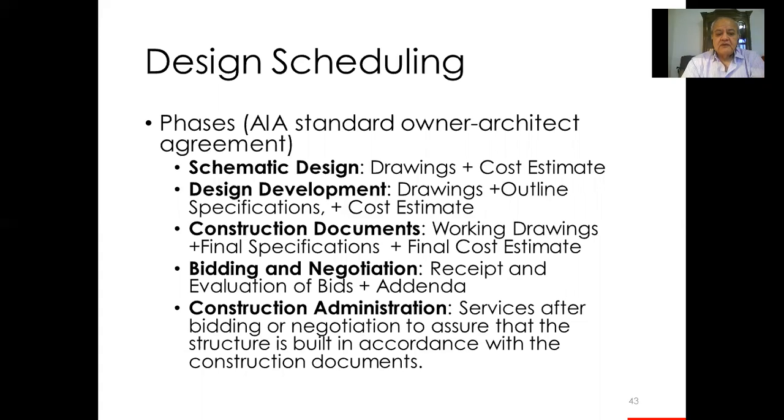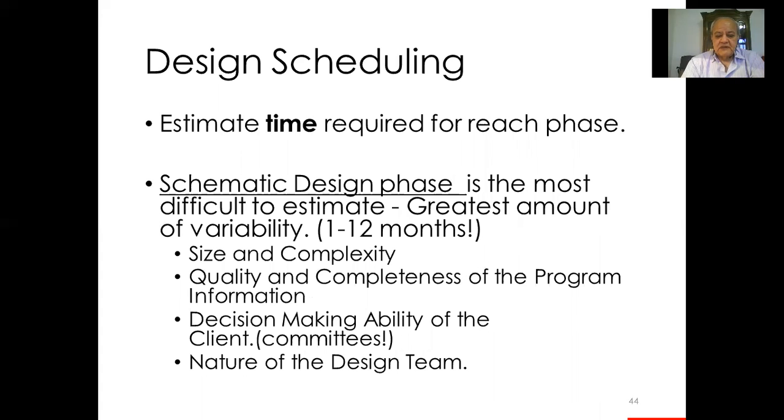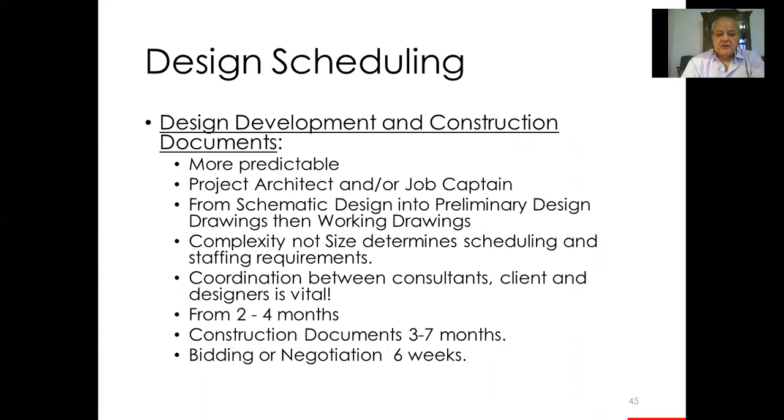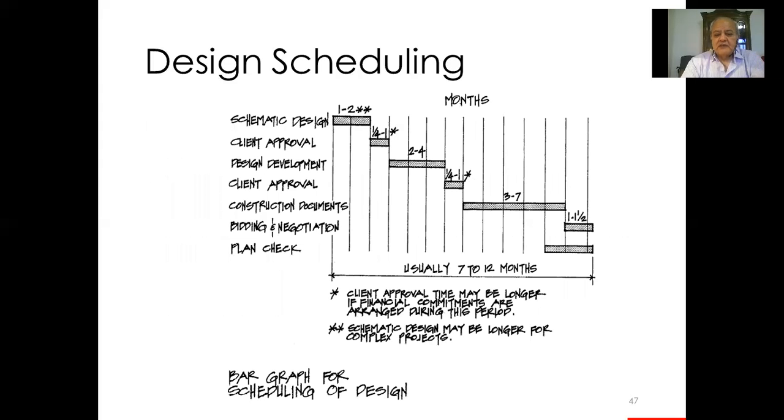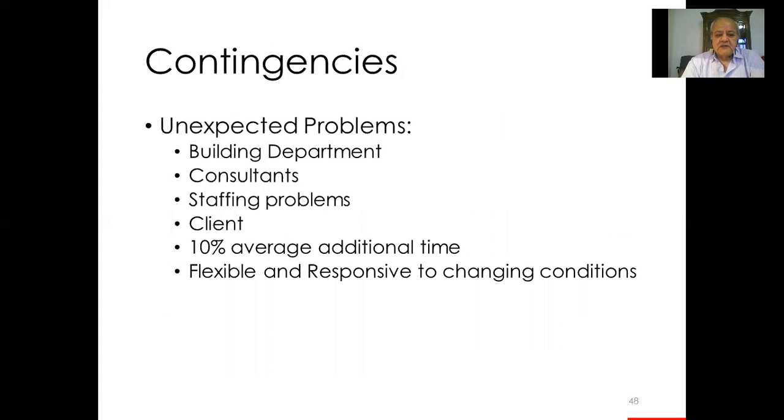We have to provide the owner with a schedule that covers these periods of time so that they can follow the progress of our work. Each stage has its detailed sub-stages, and you can provide a time schedule like this to the owner that illustrates the time schedule. You can use any simple program like Excel, or Microsoft Project or Primavera to provide schedules.